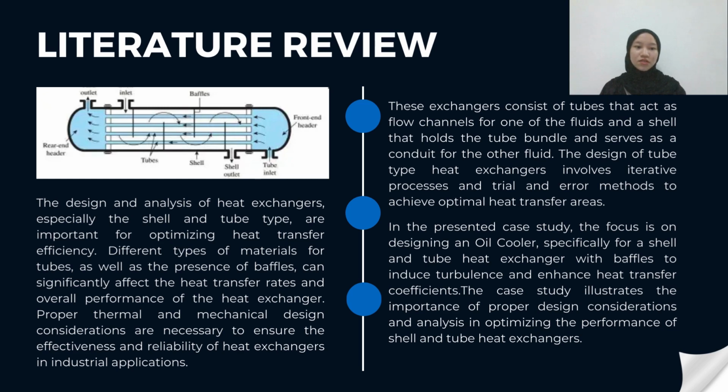This exchanger consists of tubes that act as flow channels for one of the fluids and a shell that holds the tube bundle and serves as a conduit for the other fluid. The design of a tube type heat exchanger involves an iterative process and trial and error methods to achieve optimal heat transfer area. In the presented case study, the focus is on designing an oil cooler, specifically a shell and tube heat exchanger with baffles to induce turbulence and enhance the heat transfer coefficient.